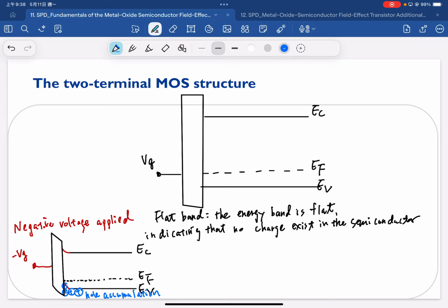This understanding is very consistent with what we were told last week, that once we give the negative bias, we always have hole accumulation. We can use the way we explained last week, but we can also use the band diagram. In the future we will prefer the band diagram because it's a very simple schematic and can be considered a universal tool that takes into account all cases, not only for silicon but for all kinds of semiconductors. So this is the case under negative voltage applied.